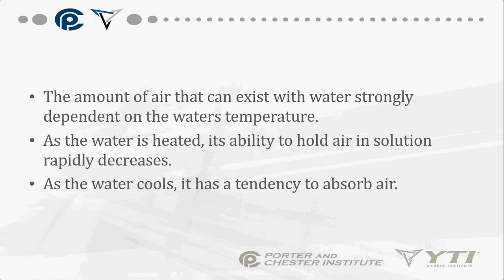The amount of air that can exist with water strongly depends on the temperature of the water. Obviously, as we heat up the water, it starts to expand. And when it starts to expand, it readily releases the air that is trapped in there. So therefore, it's much easier to get the air out when it's heated up. And as it cools, it tends to absorb air.